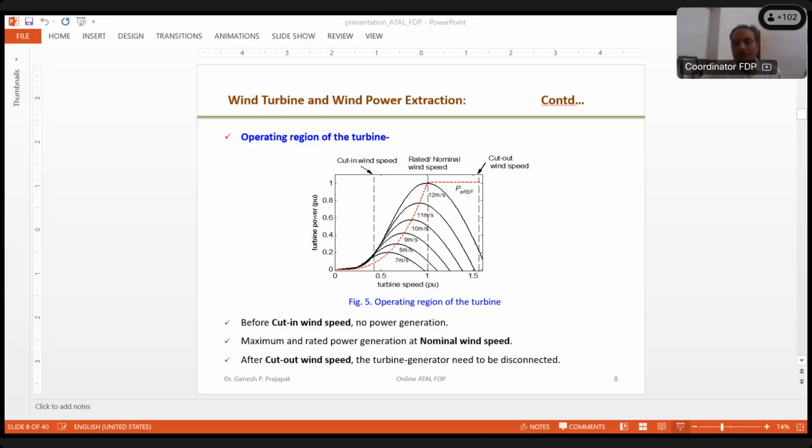These brushes will always run over the discs which are coupled with the shaft of the generator. In that way we connect to the rotor conductors on the rotor side. This happens with the DFIG only. It is a slip ring kind of induction generator, not a squirrel cage one. So we can feed some voltage through its rotor side.